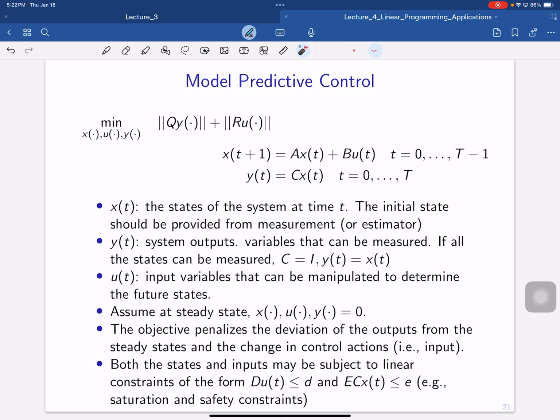Yes? So when we're linearizing the constraints, you said one case is to just discretize the derivatives. Would you also be able to do a first order approximation and use that, since it doesn't have any higher order terms? Yeah, you can do it both ways. There are more sophisticated ways in control to generate those reduced order models. Some of those are even data driven. You can derive those in matrix form, but some of those are first principle, like you said. You just derive that from the differential equation.